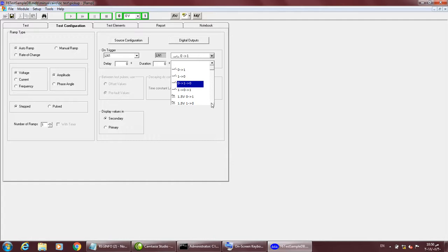010 is used when I am testing pickup and drop, so we require two statuses. 0 to 1 means when the relay trips and the relay drops, it will change from NC to NO. So this is for when we check pickup and drop both at a time. Okay. And I will show in the test how to use it. Maybe in some relays you can do it practically as well. And it is opposite: if we have an NC contact, then you have to use the opposite, 101.